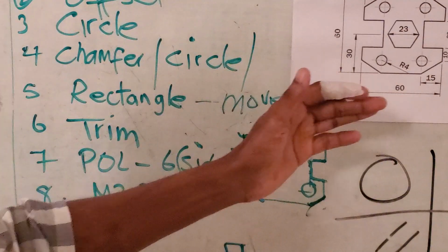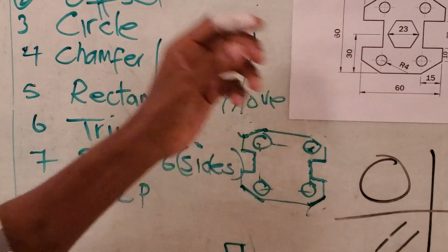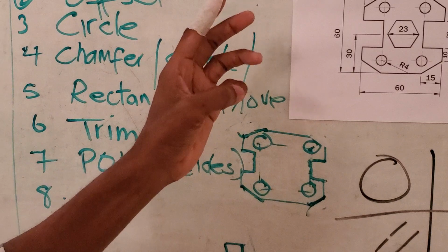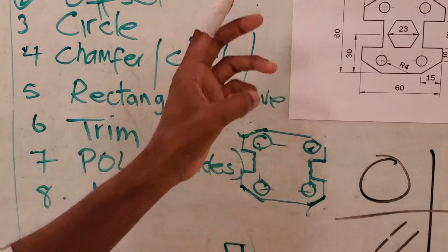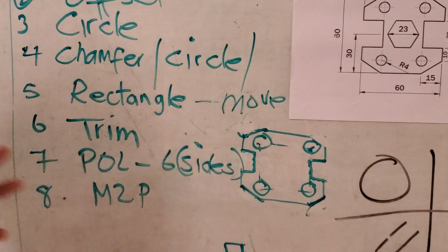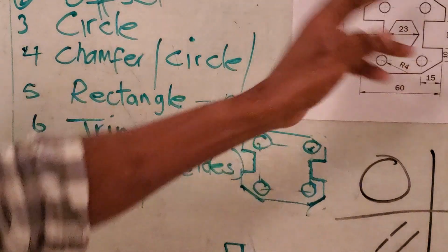All these applications or techniques are on the assumption that you have set up your drawing space. You set your object snap, which includes midpoint, node, quadrants, and stuff like that. Okay, so this is pretty much the steps that you follow in AutoCAD to draw this figure.